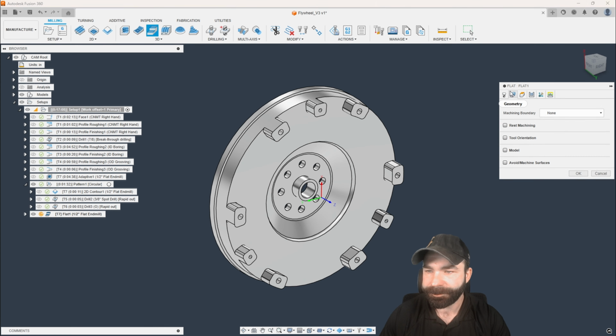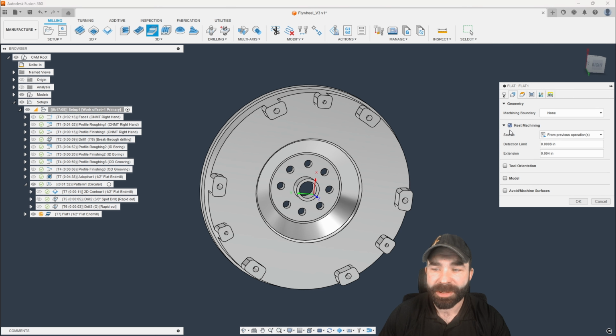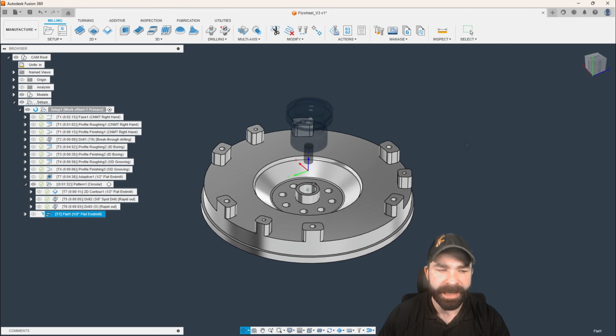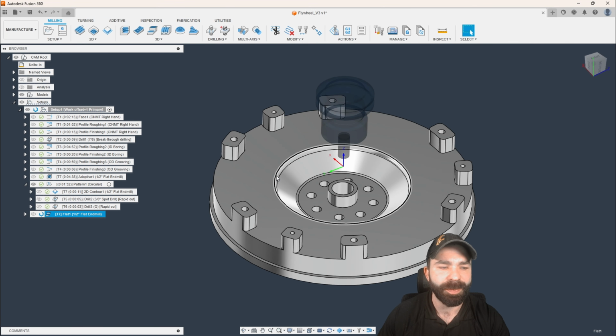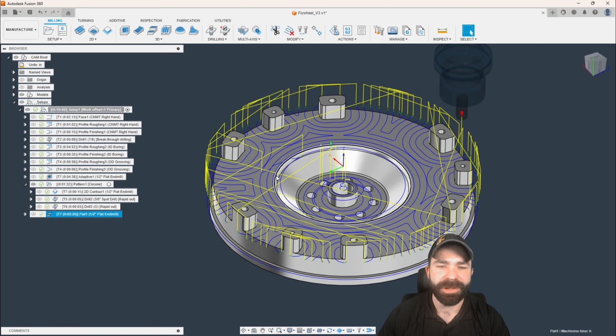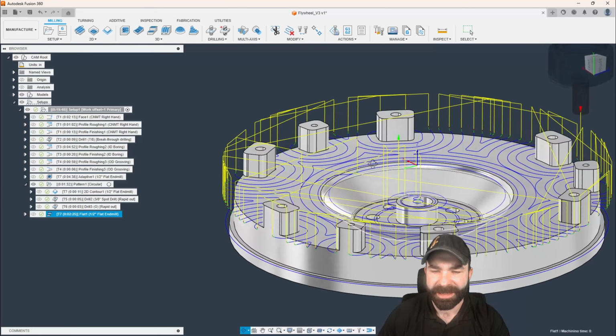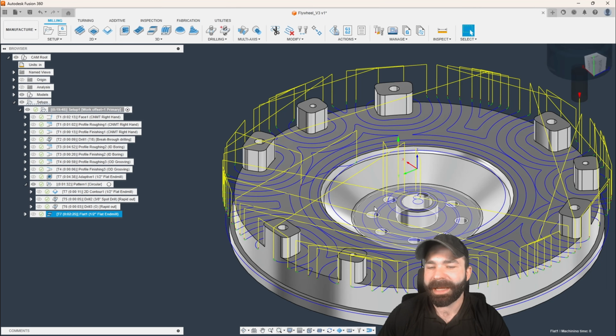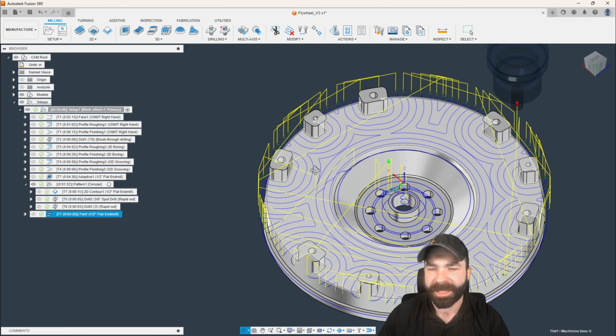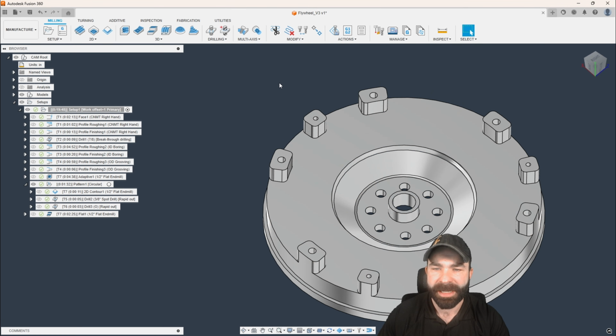The same kind of rule applies if we go back and say now 3D, let's try a flat toolpath. Again, I do have rest machining here, which is extremely valuable. However, that flat toolpath, once again, is going to recognize certain things that can cause problems and issues, right? So we'll give that a second to calculate. You guys will see that rest machining, although it is very, very handy, is still going in and recognizing a lot of faces and a lot of features I don't want. I know the area I want is between an inside edge and an outside edge.